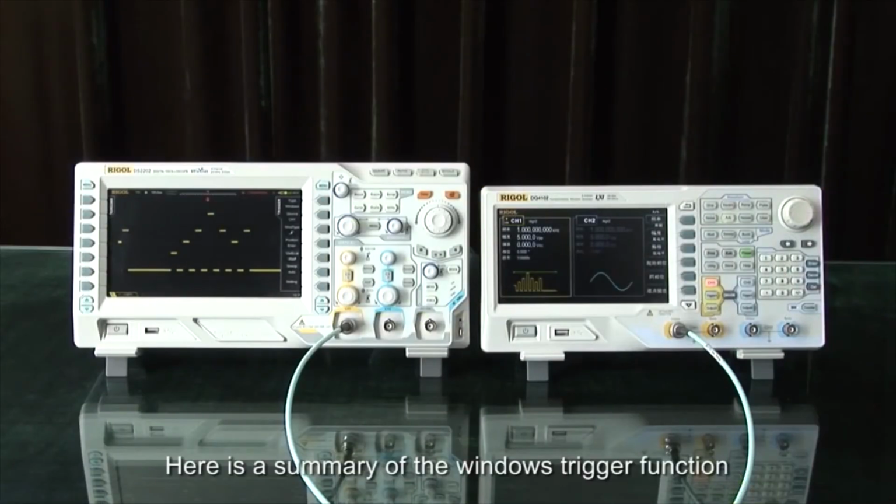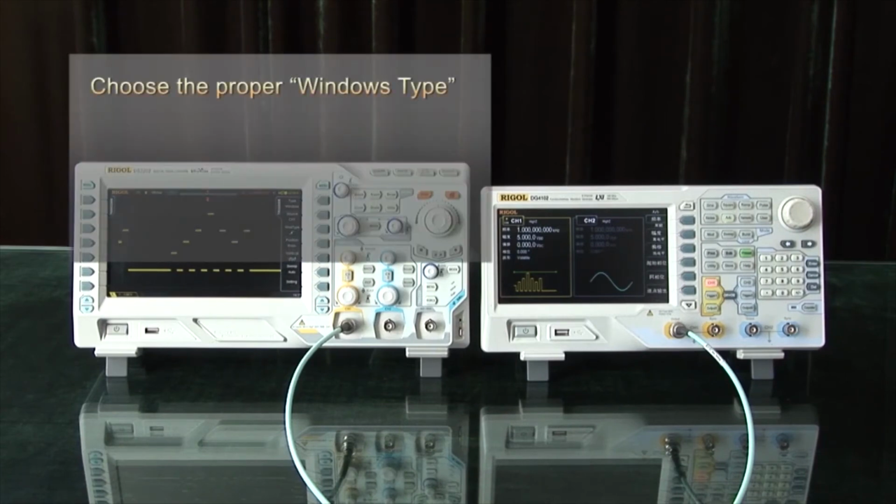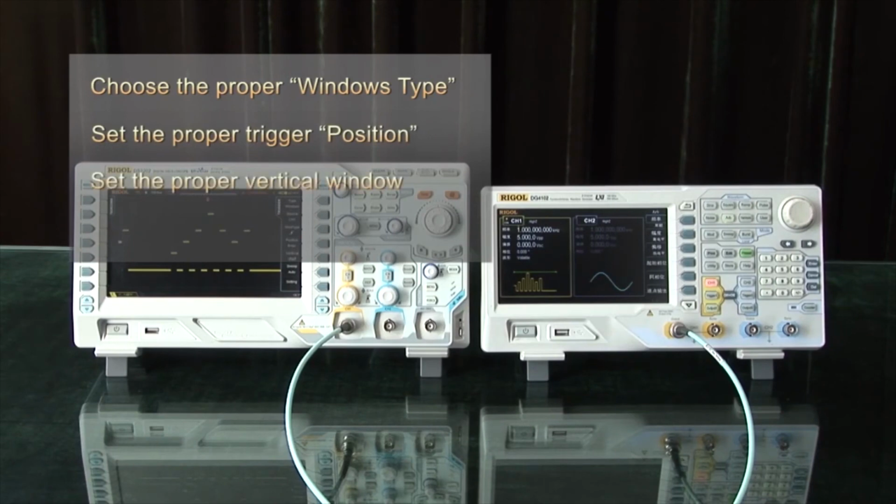Here is a summary of the Window trigger function. Choose the proper window type, set the proper trigger position, set the proper vertical window, and adjust the trigger length.